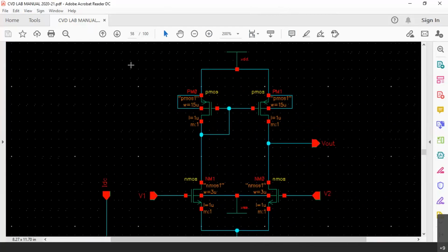Now this is the differential amplifier, and let me write the symbol for the differential amplifier. This is the symbol for the differential amplifier. Actually, inside the operational amplifier, there will be a differential amplifier, then there will be a middle gain stage, and then there is a high gain stage at the end. In general, an operational amplifier can be 2-stage or 3-stage, sometimes 4-stage also.